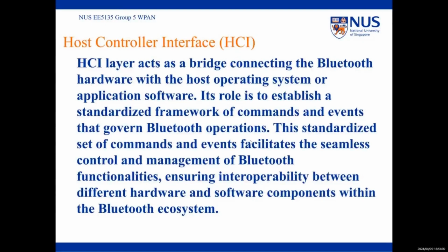The host controller interface (HCI) layer acts as a bridge connecting the Bluetooth hardware with the host operating system or application software. Its role is to establish a standardized framework of commands and events that govern Bluetooth operations. This standardized set of commands and events facilitates the seamless control and management of Bluetooth functionalities, ensuring interoperability between different hardware and software components within the Bluetooth ecosystem.